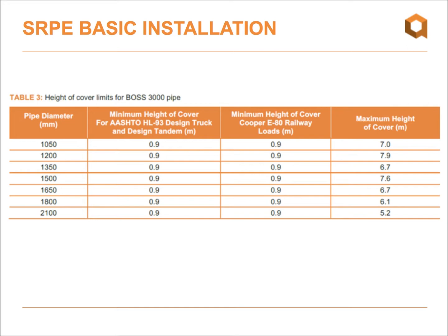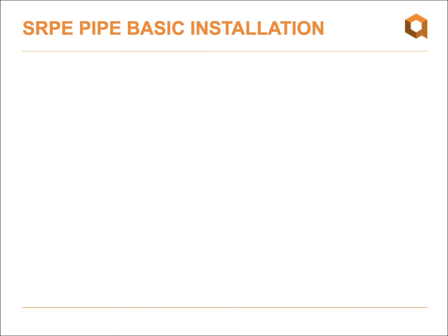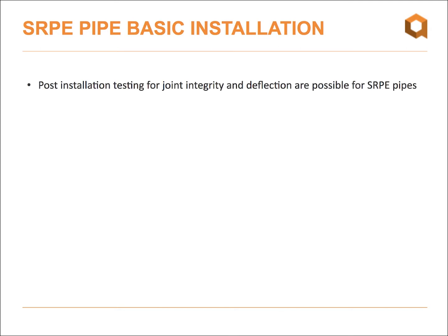Once a pipe is installed, it needs to be tested after installation. And we also provide a very detailed post-installation guideline for steel reinforced polyethylene pipe. So basically, the post-installation testing can be done to make sure that the joint integrity is good and that deflection is within the allowable